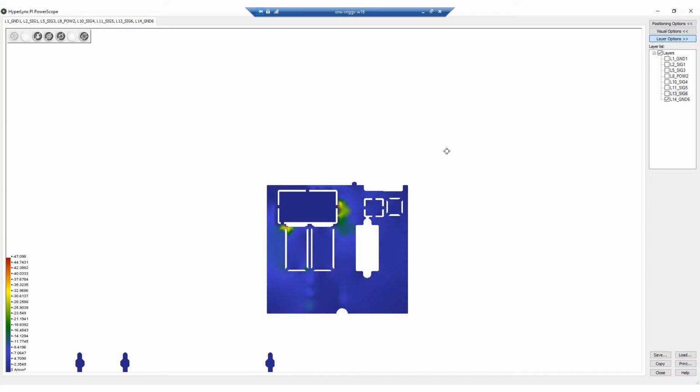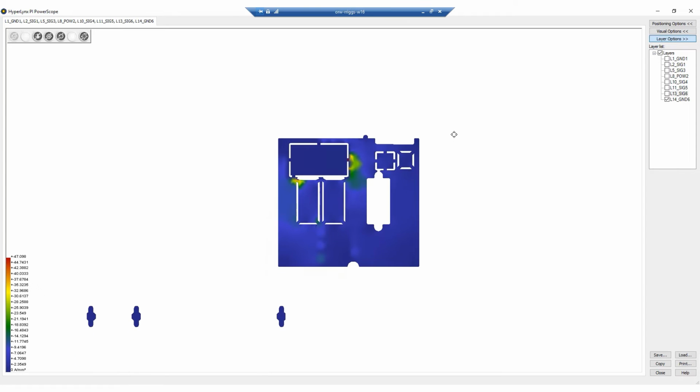This will have minimal impact on the layout designers now, but it would have been a problem with the PCB after fabrication if we didn't catch it. I will send this recommendation to the PCB designer to fix these thermal ties.